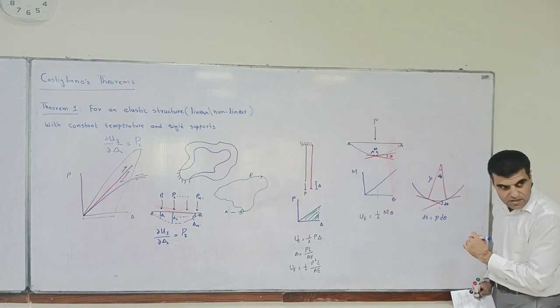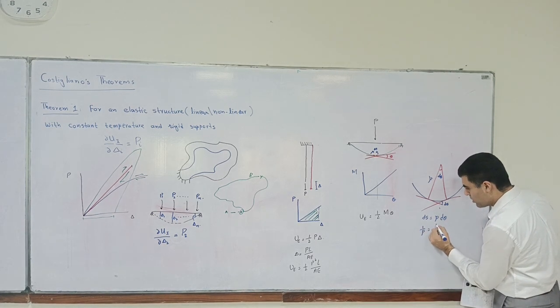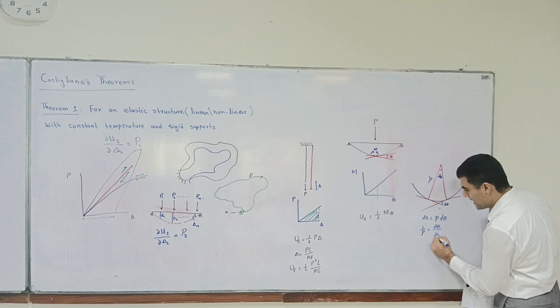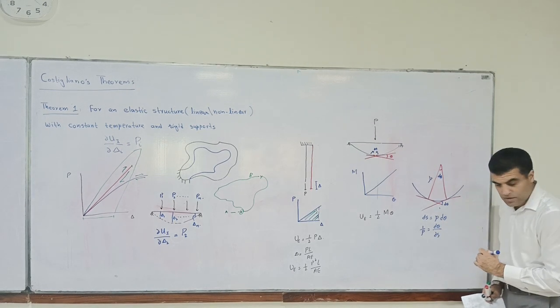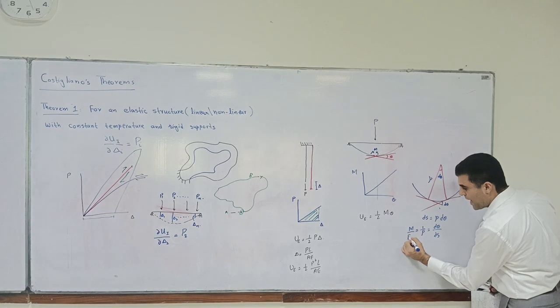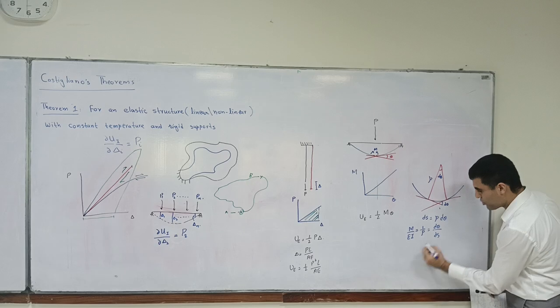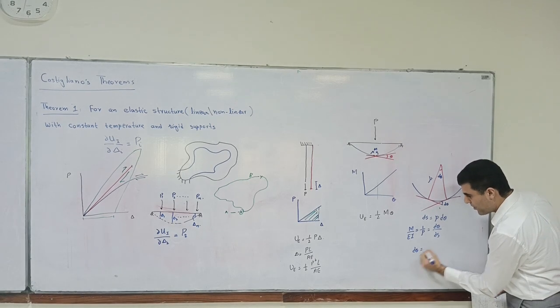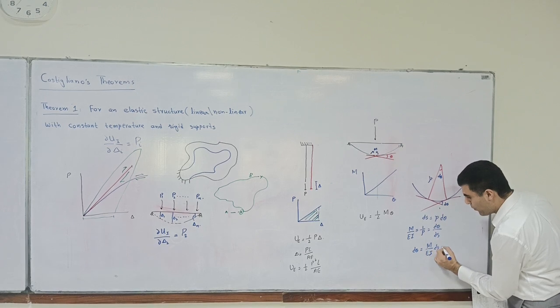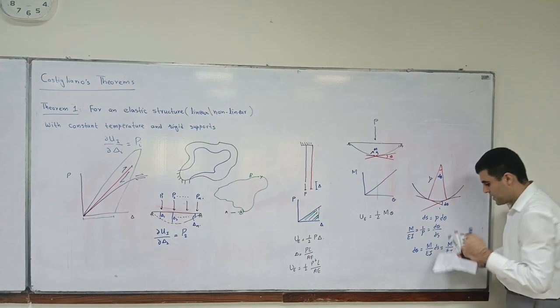Can we write that? Yeah, and 1 by rho is equal to d theta by ds. We can write that. Yes. This 1 by rho is also equal to M over EI. I think so. This should be very clear to you now. So d theta is equal to M over EI ds, which is approximately equal to M over EI dx. X being,